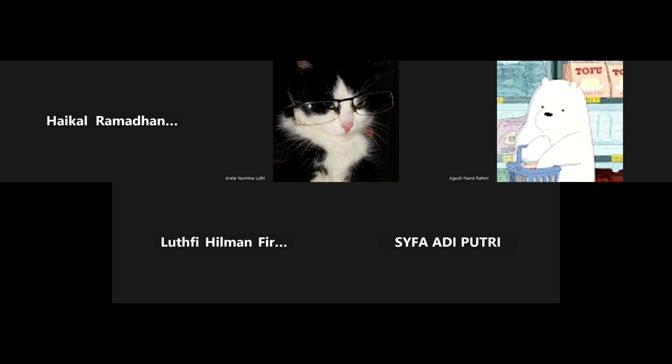And the second question from Uda Lutfi is: how often should soil cover be applied in sanitary and controlled landfills? And what are the environmental benefits? For sanitary landfills, the cover must be applied every day, or daily, and the typical thickness is 15 centimeters or 6 inches. And for controlled landfills, regularly, but not always daily. So it's not the same as a sanitary landfill. And the thickness typically depends on the operations.